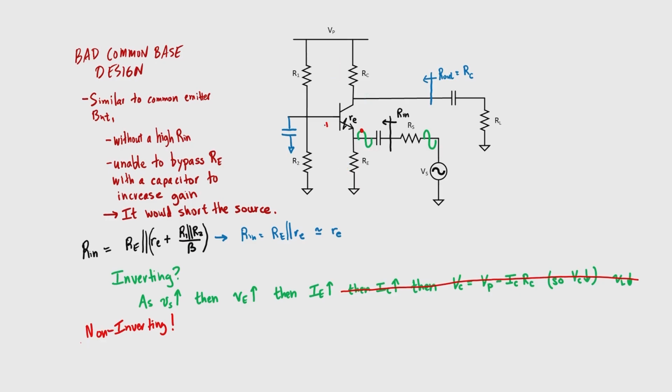Let's remove some of these details on the drawing and focus in on the base emitter voltage. I also want to label here the current going down through that transistor. I'm going to label it I. And I want to make a little graph of what happens to that current I as we change the voltage across the base emitter junction. You might remember that that's a p-n junction, so it's just a diode. If the base emitter voltage drop is too low, then no current will flow through the transistor, but once we hit the threshold value, which is about 0.7 volts, then we have a huge amount of current flowing through the transistor. Let's say that we start at a particular operating point on our curve.